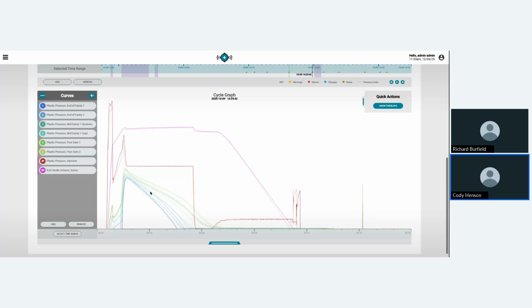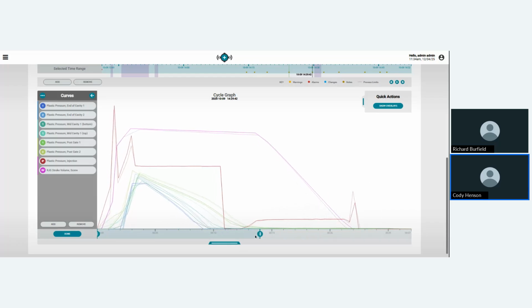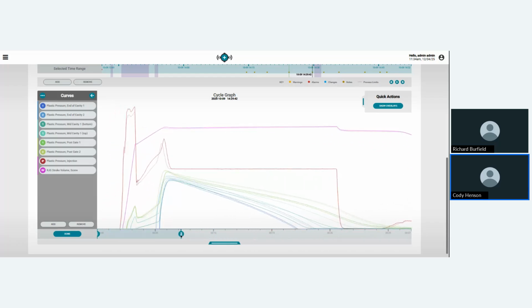And you will be viewing your hub with a keyboard and mouse. So this is a time where you will need to select this time range. Right? You won't have the option of touchscreen most likely. And then you can zoom in to your cycle just like you would and start to see some differences in how the machine must have gone to a lower melt flow, right? As it used less pressure as we changed the melt.